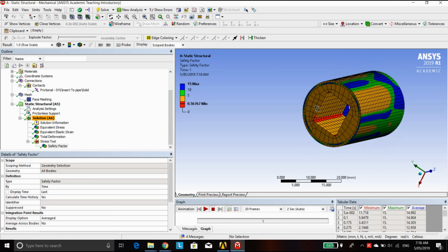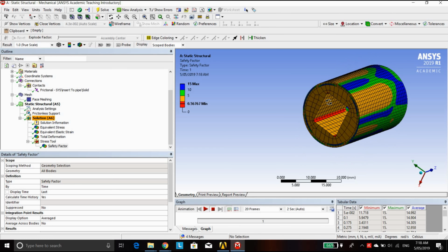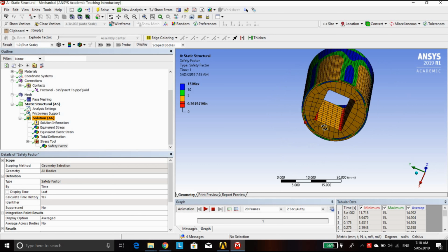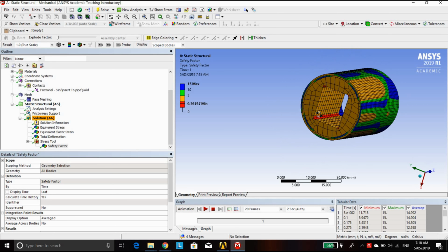So by pressure fitting the polyethylene inside that pipe, it is going to start breaking and cracking from those corners, and we're not going to have that much life for that material.